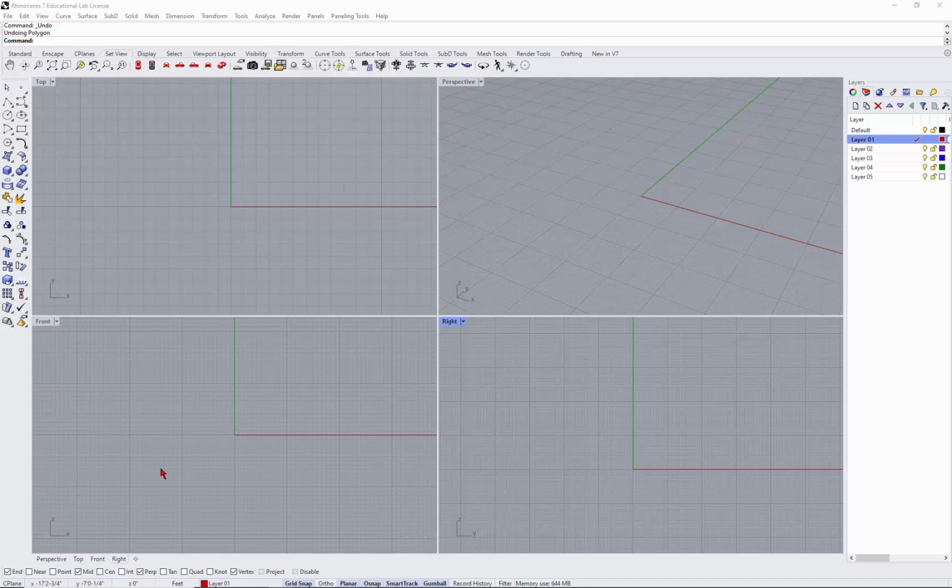All right, I'm going to go ahead and create the loft that we talked about and move through the process in Rhino, and then we'll move into Grasshopper. So the first thing I'm going to do is I have layer 1 current, and I'm just going to make the polygon with the 7 sides, just make a small one here.